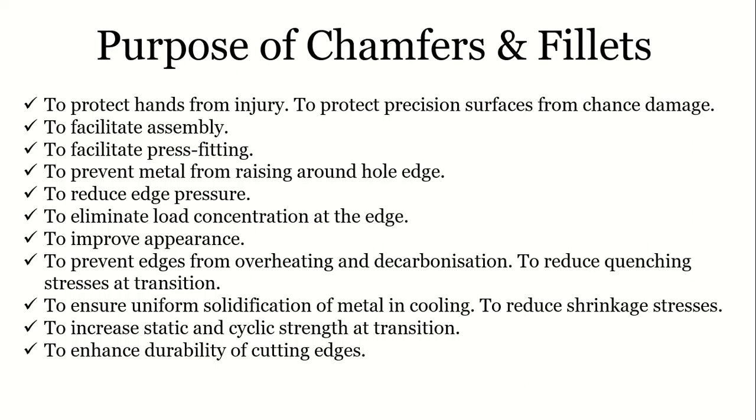So basically chamfers and fillets are provided to protect the hands from injury and to protect precision surfaces from chance damage. While handling components with your hand, if they have sharp edges, your skin might get damaged. To prevent that, and to facilitate assembly, to facilitate press fitting, and to prevent metal from rising around the hole edge, which happens during press fitting, chamfers and fillets help reduce it, and they help to reduce the edge pressure. They help in eliminating load concentration at the edges, and they improve the appearance of the component.